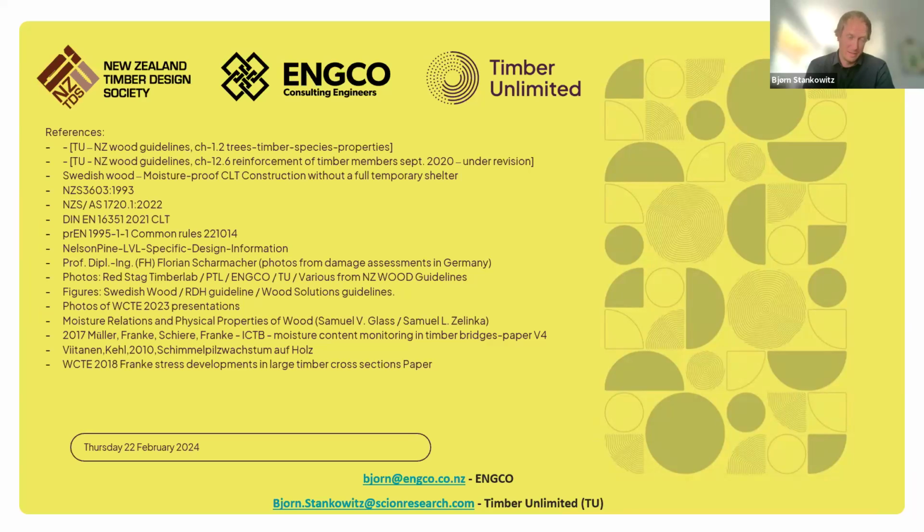I agree with the comments. One thing to add: if you measure relatively frequently, you want to think about getting a calibration pad as well, because nothing is really working well if it's not calibrated and you're not 100% sure it's working. The other thing is that surface temperature does affect the reading quite significantly. So you probably also want to get one of these infrared thermometers. They're quite cheap, but that allows you to dial your calibration up or down. Most moisture meters these days have it in the digital ones; the non-digital ones, I'm not quite sure if they do. There are some correction factors you can apply afterwards, so some post-processing is required, but in general terms, the temperature, especially in winter or in very warm areas, should be adapted and adjusted.